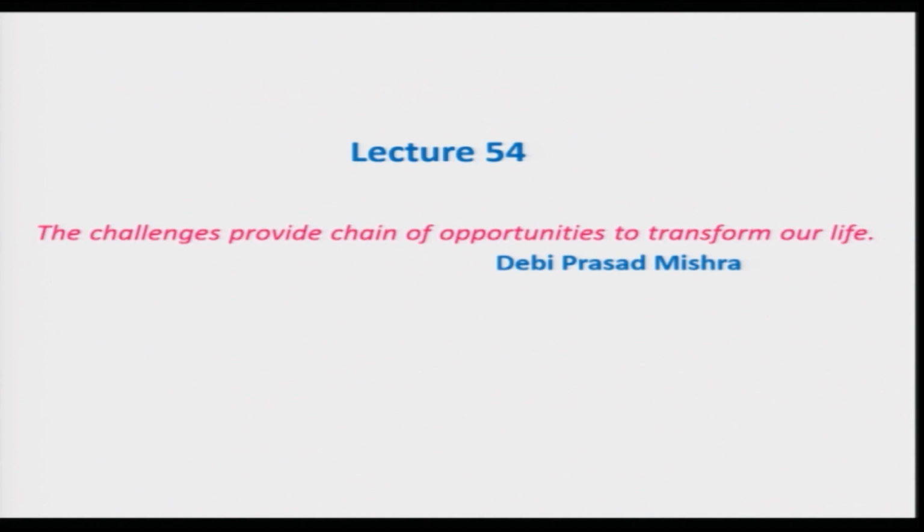Let us now recall what we learned in the last lecture. In the last lecture, we initiated a discussion on cooling system of rocket engine, asking a question, why we need to cool the thrust chamber and the nozzle of a rocket engine. And we learned that the main reason is the non-availability of the material which can withstand high temperature and stresses, or the stresses due to the high pressure and high temperature gases in the combustion chamber and nozzle. That means, if we can produce better material in future, we may not need to have a cooling system.